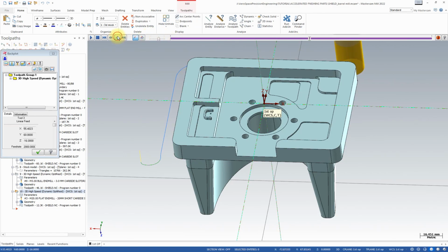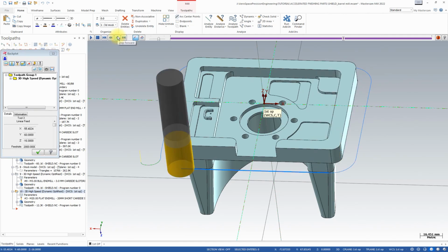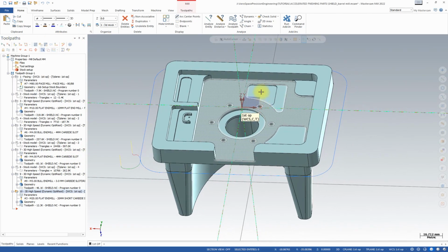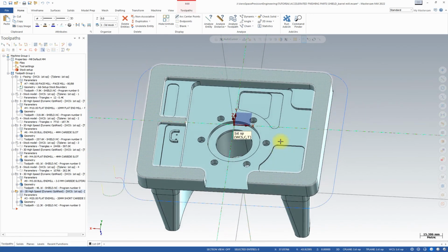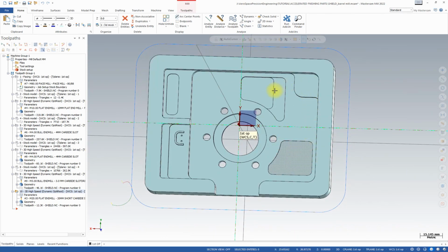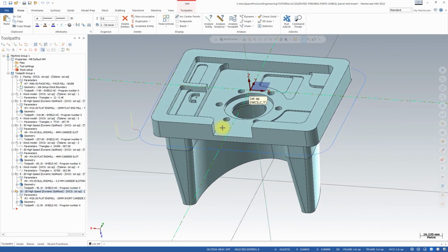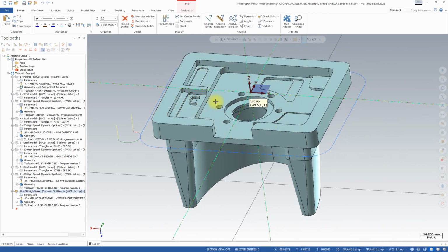So, straight line, round, straight line, round. That's good. Okay. Of course, we would probably cut all these faces to finish all these faces around with a contour toolpath or something like that, just to have the compensation possibility on the machine. But I'm just wanting to show you how to quickly generate the toolpath for quite a complex, quite busy 3D model.